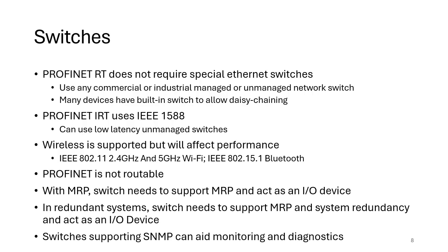So you might have several cables which might have failed and several switches on a very long run, and you won't necessarily know where it is. So it's better to use MRP and maybe even a managed switch with SNMP, the Simple Network Management Protocol, and that will give you better diagnostics to understand which device has failed, and that will allow you to recover more quickly.